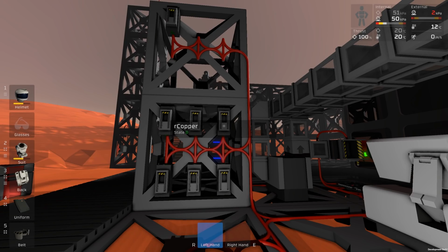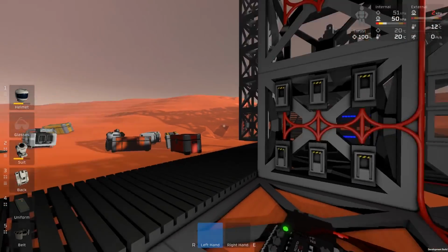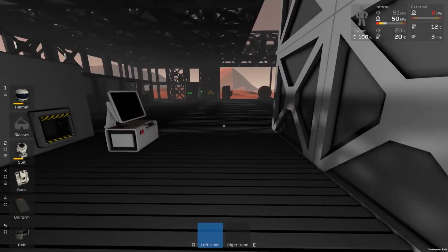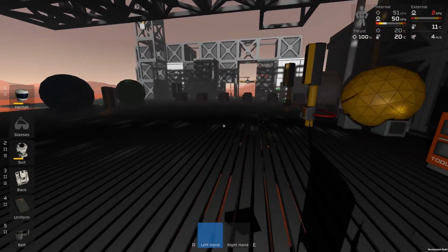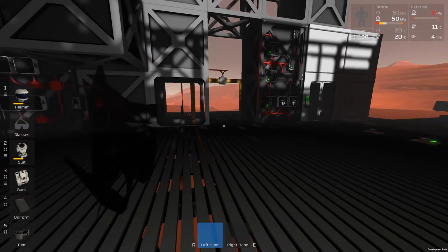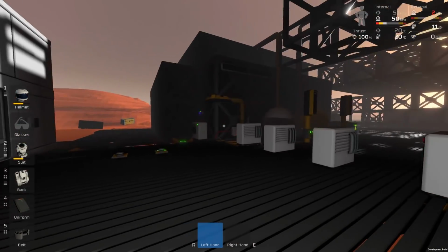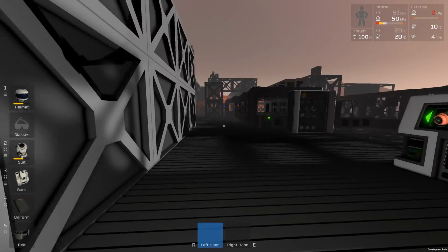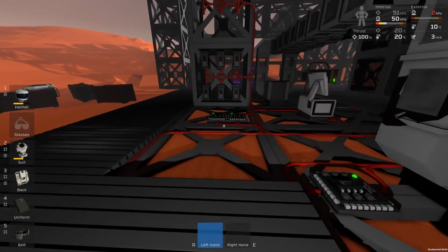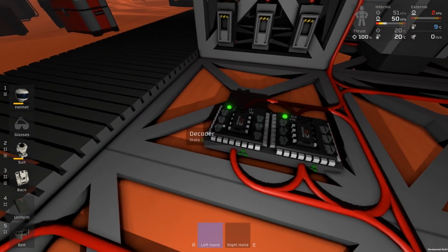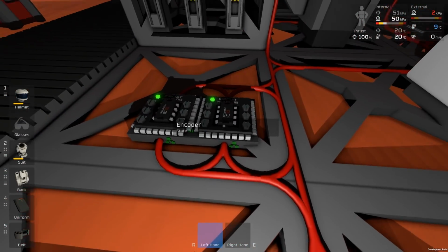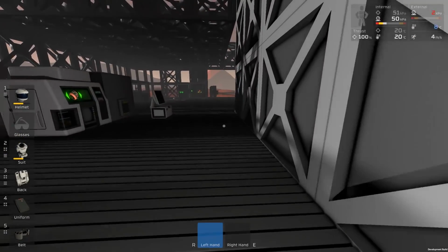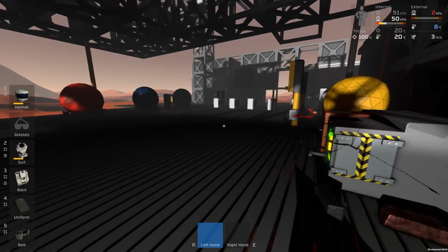Because we're not going to be using switches very often, we're actually going to be tracking various values. If I can just quickly look at the encoded value and say, yeah, I know roughly what those values are, I've set them up, so I can easily see which things are on and off, and still only using one pin, I'm happy about it. If you want to just store the encoded value as decimal instead, that's no problem. You have to do a little bit of different code, but you're basically converting from binary into a decimal value and then back into binary again. And that's generally a lot of divisions and mods to get back to binary and separate all the variables again.